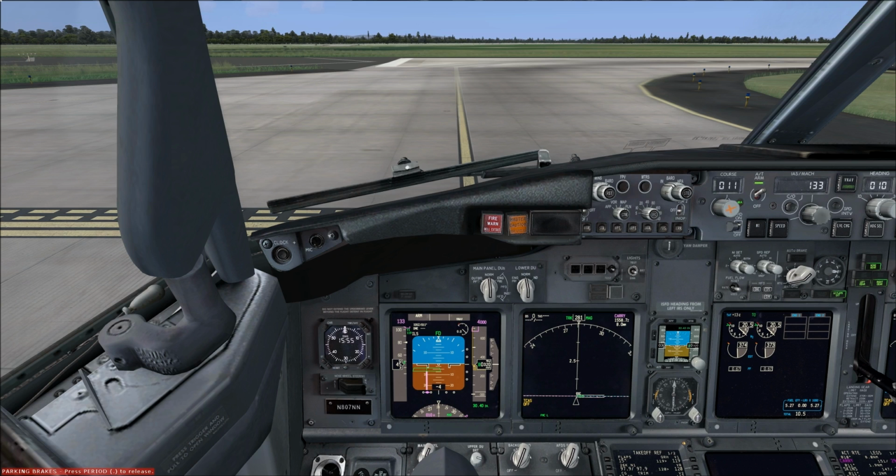On departure, specifically the takeoff mode, if the microburst occurs behind you, you'll notice a very slow buildup of indicated airspeed combined with a fast buildup of ground speed, as the tailwind would push you down the runway. Now this is dangerous for obvious reasons, because if it's not recognized early enough and you try to continue to take off, you could run out of runway before you get to VR. Or if you were to try and stop on a main runway, you could be traveling too fast and end up off the end of the runway.